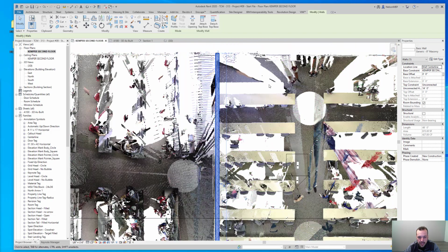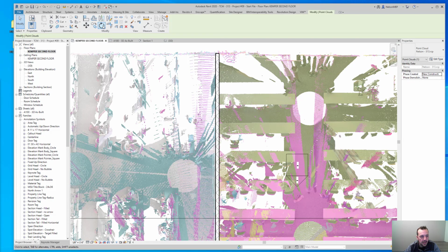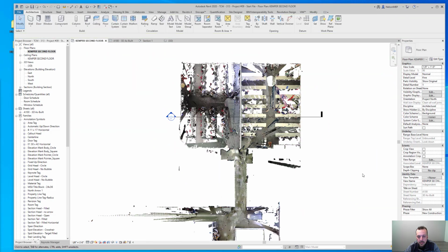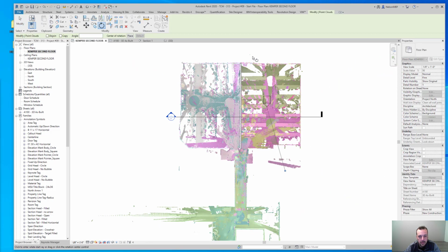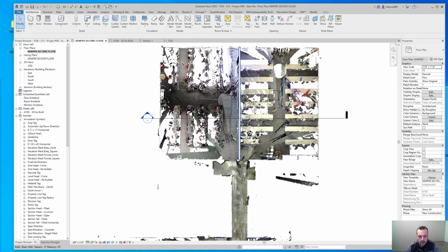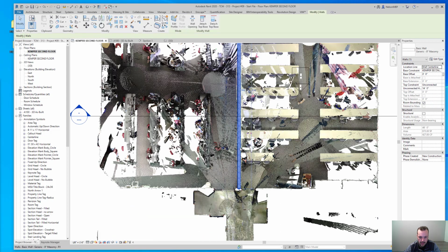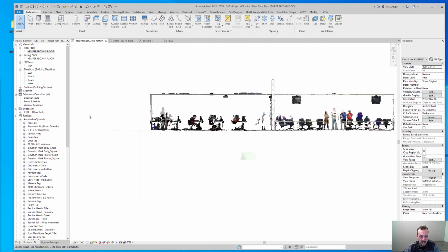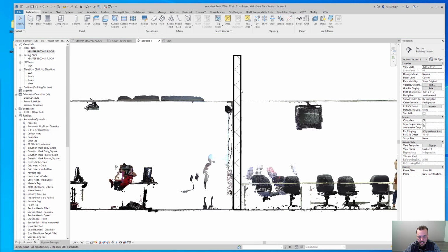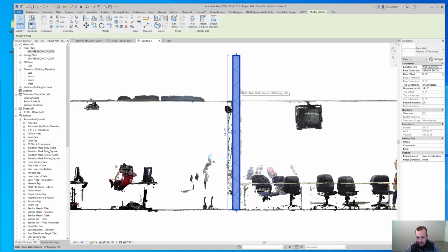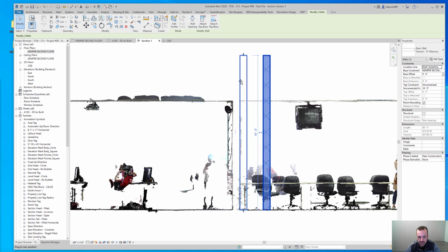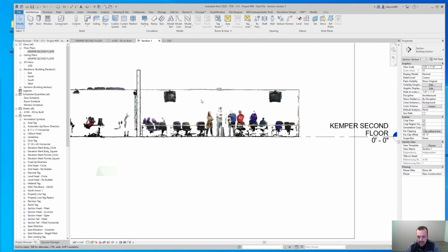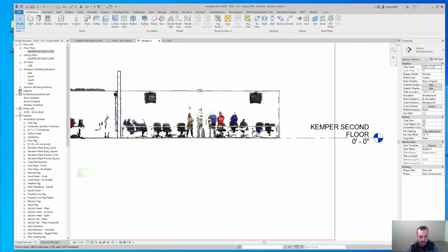Looks like the point cloud is just a hair off. Got it set. Can look at my section. See that's extending up. That's okay. We didn't really look above. But as I move that, you can see, well, here's my gap. It's pretty much an 8-inch wall between the two. So now everything is set. Then you can do concrete wall. CMU is fine for everything here.